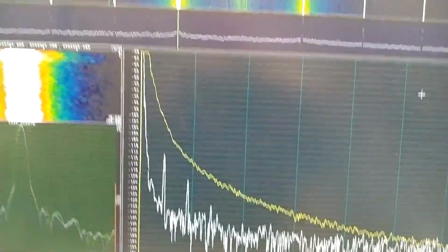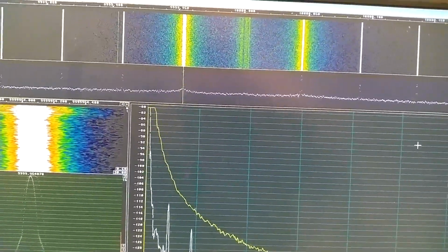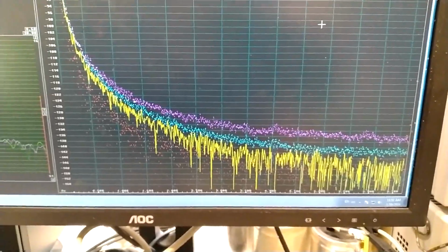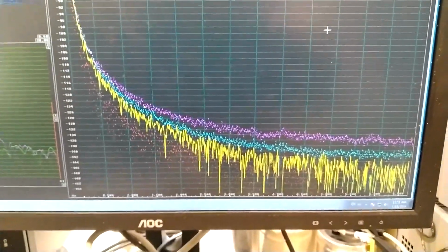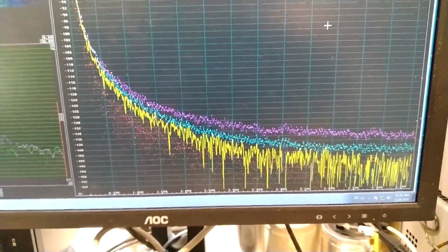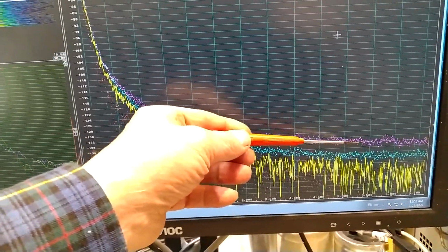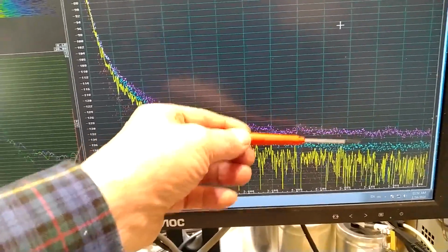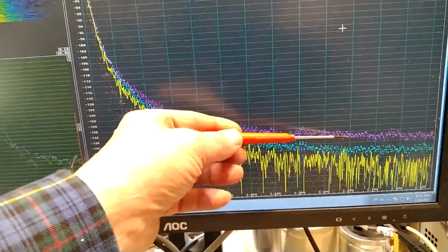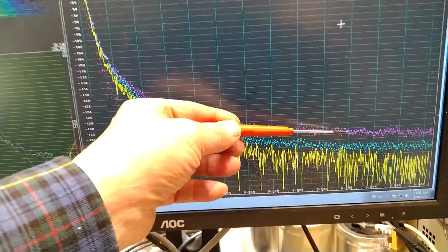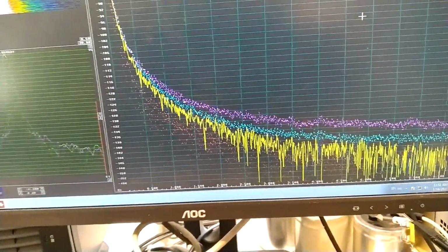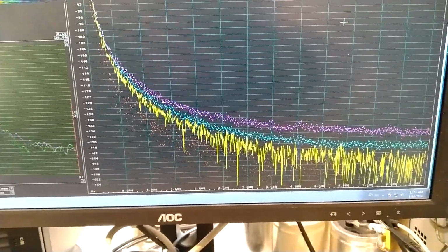So I will check to swap the oscillators. Now channel 1 is the better one. So obviously the sensitivity for the correlation measurement in this region, around 5 Hertz, is limited by the mixers. So better mixers would be a good thing.